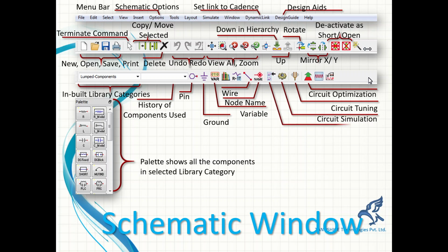Here you can run the simulations, and this one is for when you have multiple schematics for the same cell, so you can choose which schematic you want to use. Usually what happens is, if you have multiple implementations of the same circuit and you are analyzing a system, then you have certain policies which you can launch, which automatically select which schematic you want to use. This is for optimizing the system performance, and hardly people use it or talk about it, but we are going to do that.